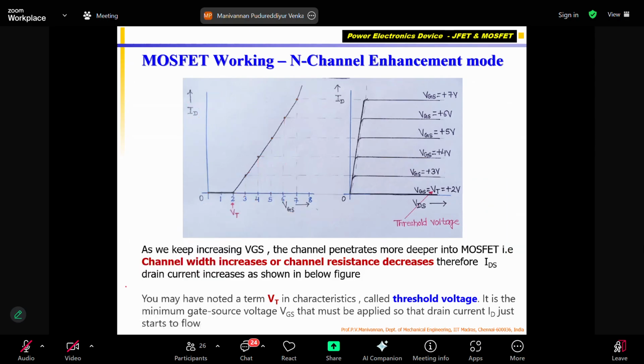Okay, so this talks about input versus output. Current varies. Now also on the input side, you can see that I keep my VGS equal to 2 volts, the input voltage, and I vary my drain to source voltage, just like VCC was varied in the case of a transistor. 0 to, for example, 100 volts for this MOSFET, correct?